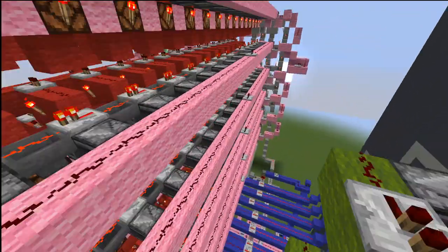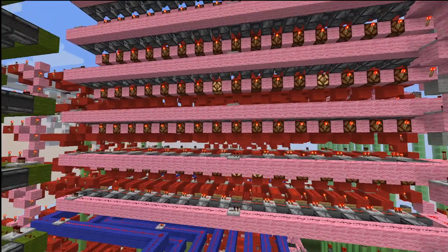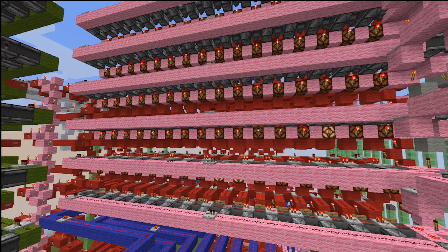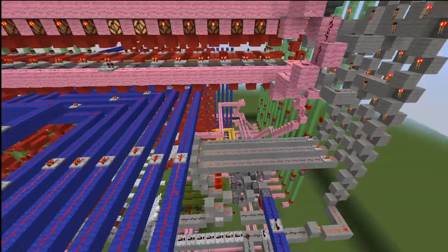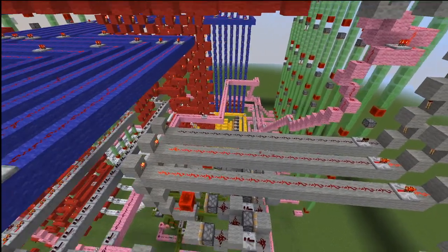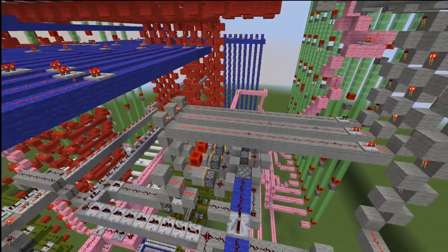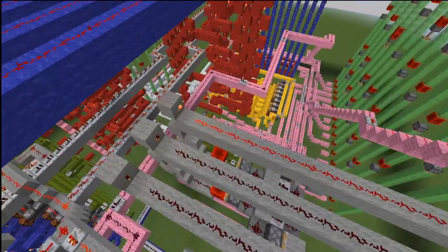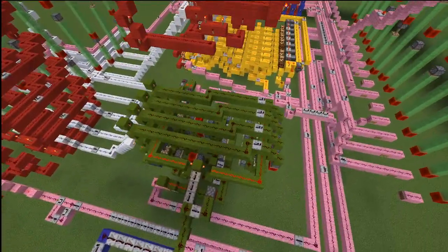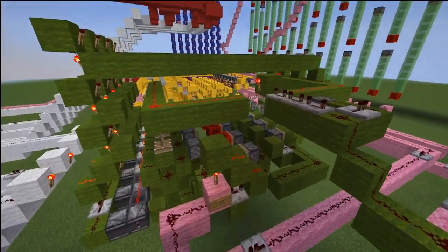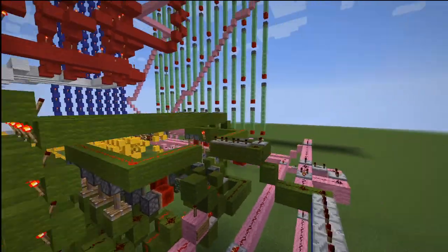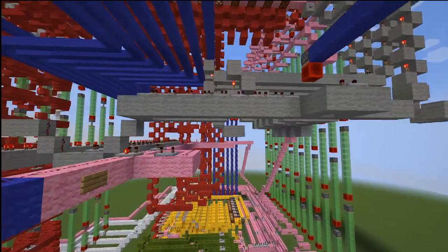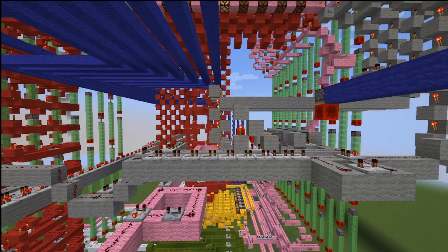So now we can see the instruction set is actually going to change. The instruction register here is going to update the control unit instructions, which we'll see. And it just updated it. And now on the next line, it's going to increment the program counter. So we'll get to watch that. So if I come down here, it's going to increment this. So it'll increase the program counter to 9, which it just did. And we can now come up here, and for a no operation, that's actually it.